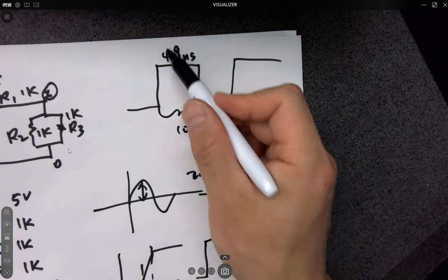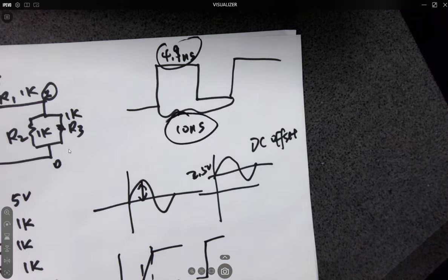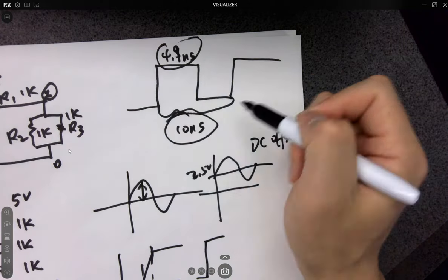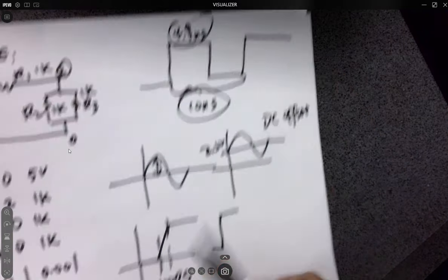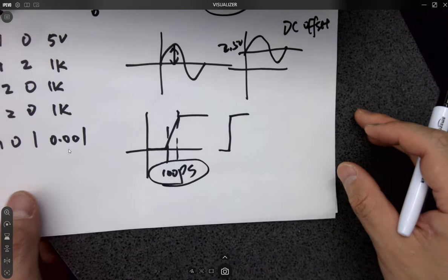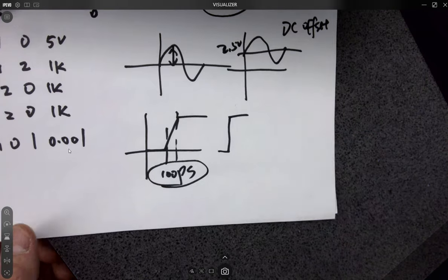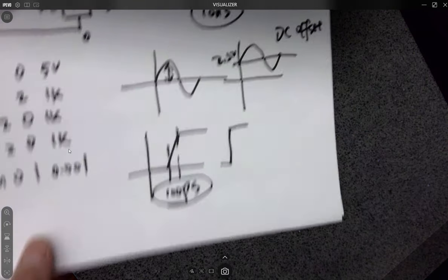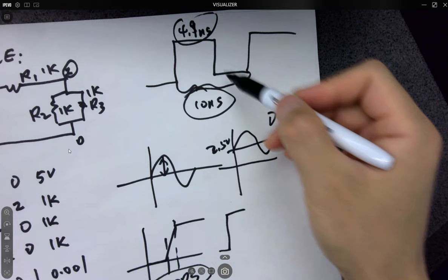It's not 5 because this is 10. I think if you give a 5, it's going to show some errors over here because you're having a little bit of time loss for the rising and falling edge. So it won't be exactly 10 nanoseconds or double that on time. So give a little bit of room for the computer to resolve.